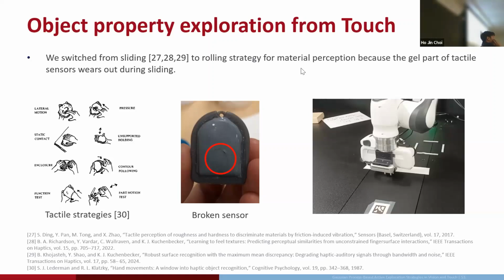Yeah, this is a very good point. For example, if you have an RGBD camera and you go closer to the surface, you can get a better estimation of the depth. There's a kind of quadratic relationship between the noise of the depth observation and the distance from the camera to the object. I haven't shown the slide here, but the Gaussian process formulation I showed assumes a uniform variance of the observation points. You can actually incorporate the input noise in this formulation and have a different variance on each data point. I haven't done it, but I believe you can try that kind of exploration strategy, where you go closer and farther using the GPDF. But in this work I haven't explicitly mentioned it.